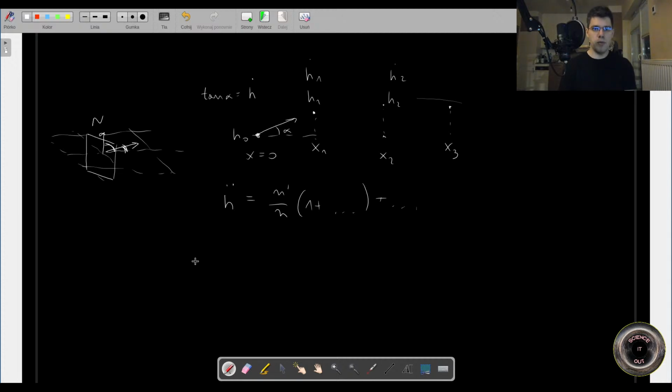Nowhere here do we have the precise coordinates of where the ray is on Earth, but knowing the initial coordinates, so knowing the latitude and longitude of the starting point, and knowing the azimuth, so the azimuth also enters here, and knowing the distance, so basically knowing this x, we can calculate what is the latitude and longitude of the final point.